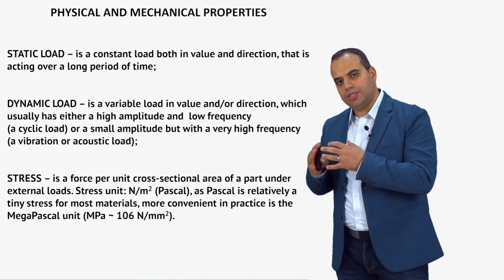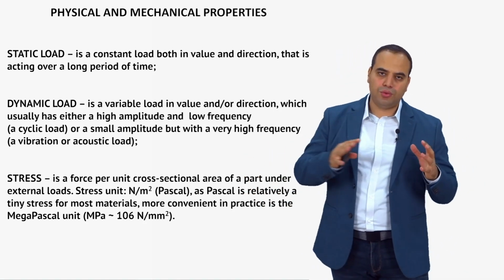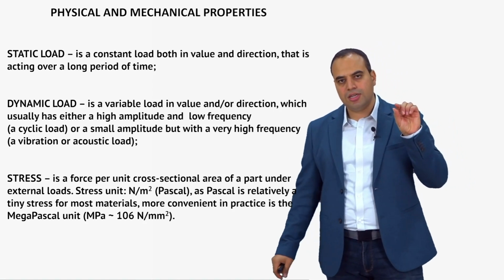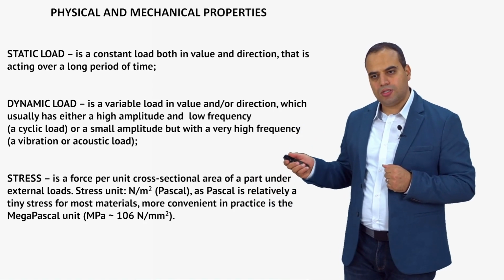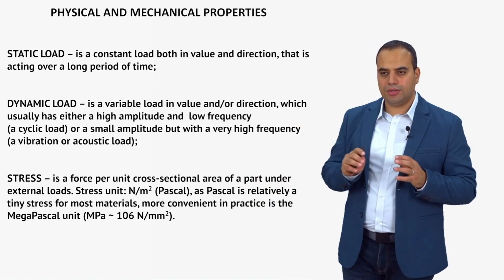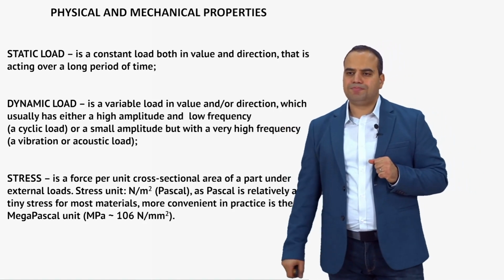So if we have a lot of material but the force is small, that means that stress is going to be small. If we have a lot of force but the material is little, so for example, a thin structural element, then that means that element is going to be stressed, right? Why? Because it is a force in a single cross-sectional area. It is a force divided by the area, right?